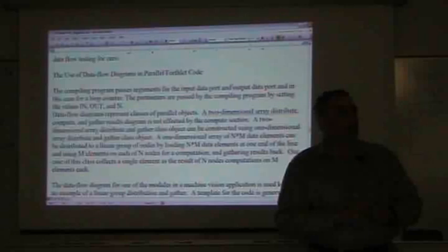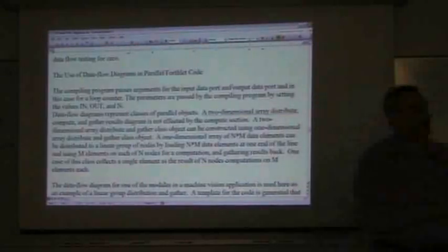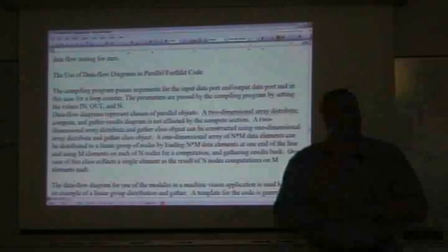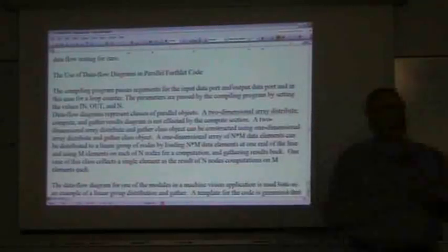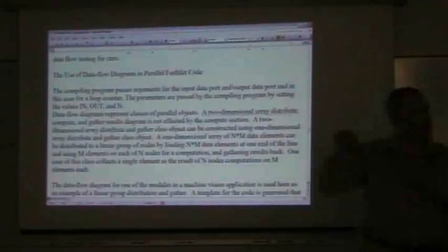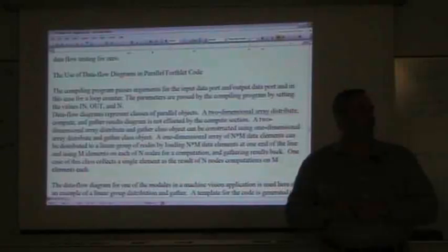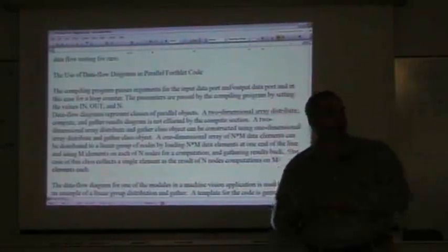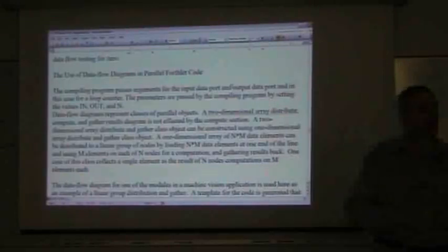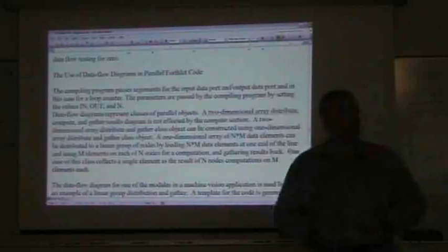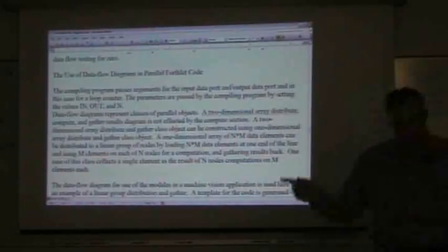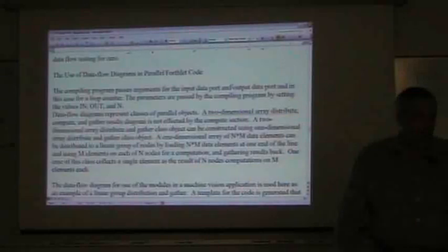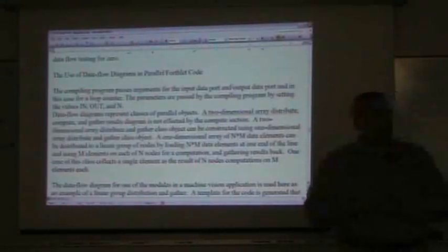So I said what we should do is reduce the pixel traffic, which was our bottleneck, by a factor of 6. We send out 18 pixels, and then from that point on, we just send out 3 pixels just after the group has rearranged its pixels in preparation for getting 3 more. So each time we just send out 3 more, and now it's got a new group of 18 pixels to work on, and then we send out 3 more, and each group has a new arrangement of 18 pixels to work on, and it sends its results down to the end where things get collected and get turned back into a video image.